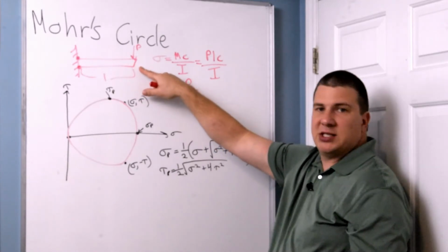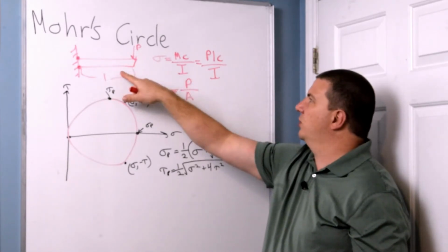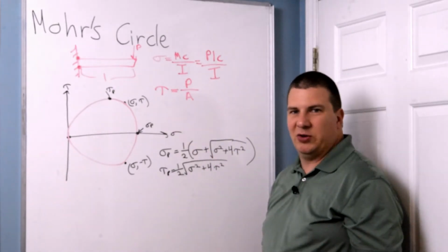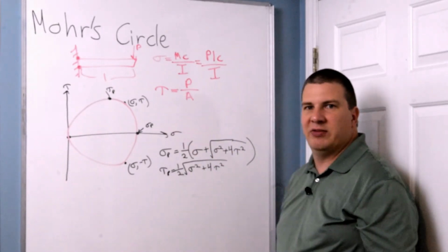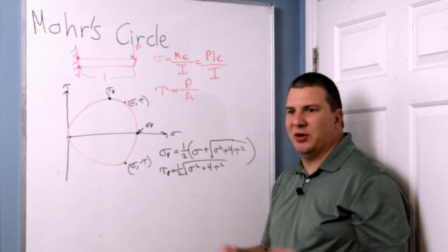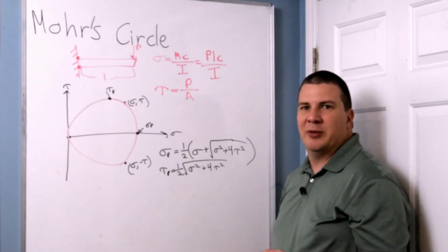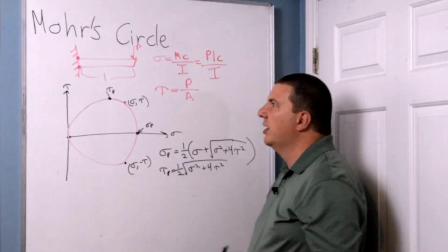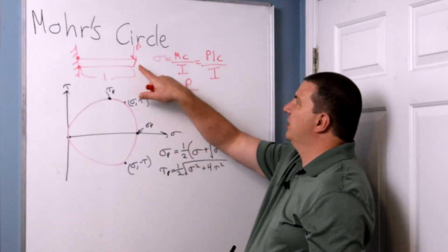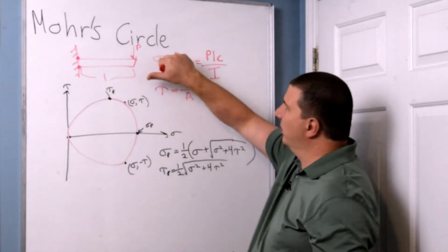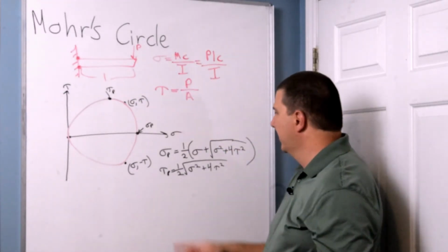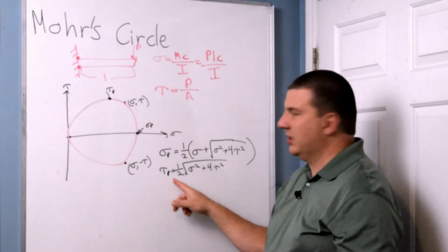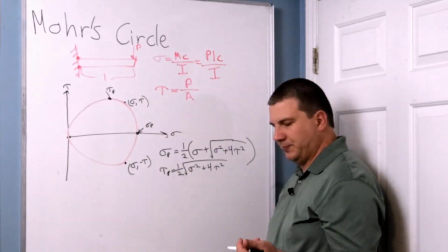Alright, and in most cases, the bending stress will be so much more than the shear stress that we wouldn't even necessarily calculate the shear stress in there. It's such an insignificant factor. You know, it might add 300 psi or something of that nature. So a lot of times we'll just leave that out. However, if this was a beam that was in bending and torsion as well, we're putting a torsional member in here, moment in there, this number might be a lot higher, and it could even exceed the bending stress.